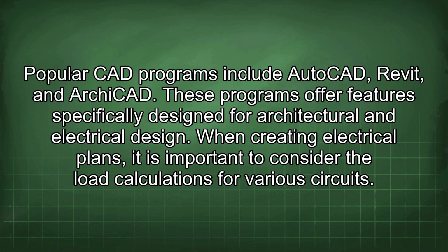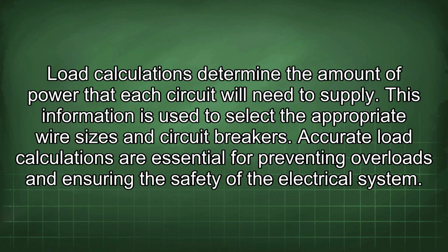When creating electrical plans, it is important to consider the load calculations for various circuits. Load calculations determine the amount of power that each circuit will need to supply. This information is used to select the appropriate wire sizes and circuit breakers. Accurate load calculations are essential for preventing overloads and ensuring the safety of the electrical system.